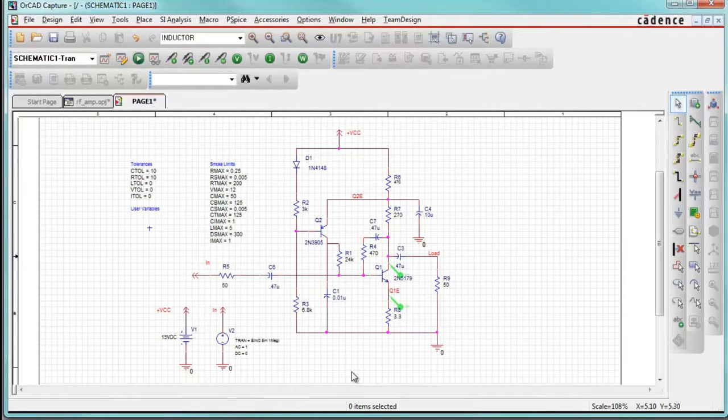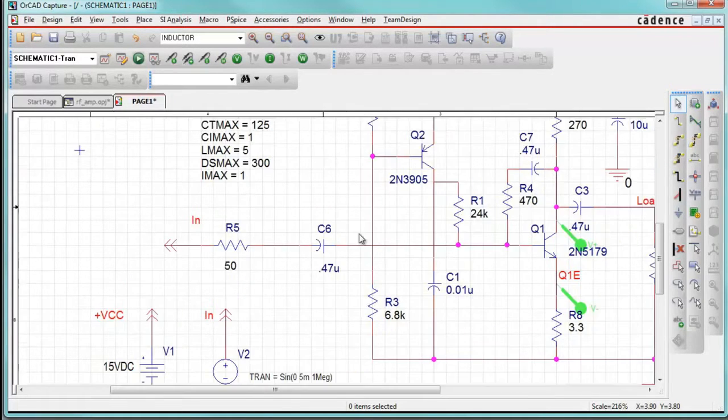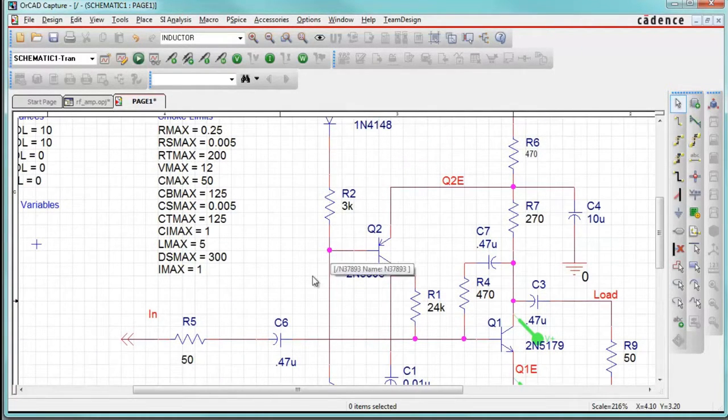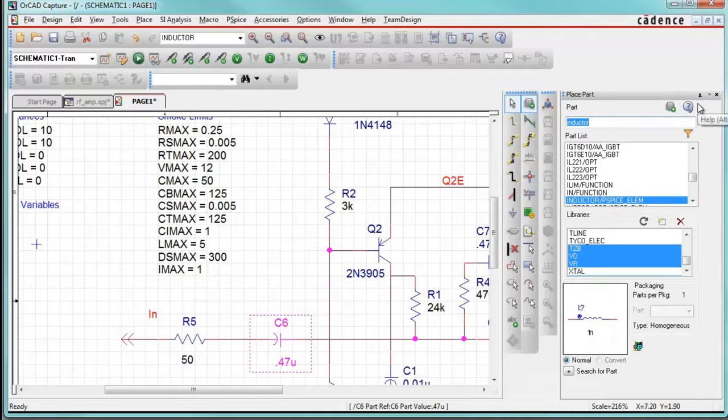For smoke, what we want to do specifically is say what the limitations of our components are, and then run a simulation like I just did and see how far I've pushed my components. To set your limitations for your components, the easiest place to start for passive components is to just use resistor parts or capacitor parts from the PSpice elements library.